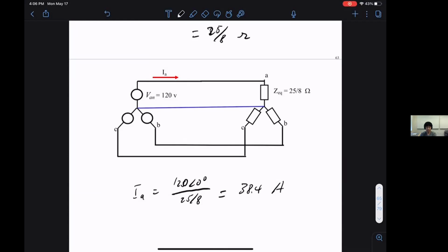In practice, of course, you will also have different types of generators in one system. For us, we will not have that. We'll stay mostly with one generator and multiple different types of loads. So there is always a clear idea of what to convert to. If your generator is delta, convert all loads to delta. If your generator is Y, convert all loads to Y.